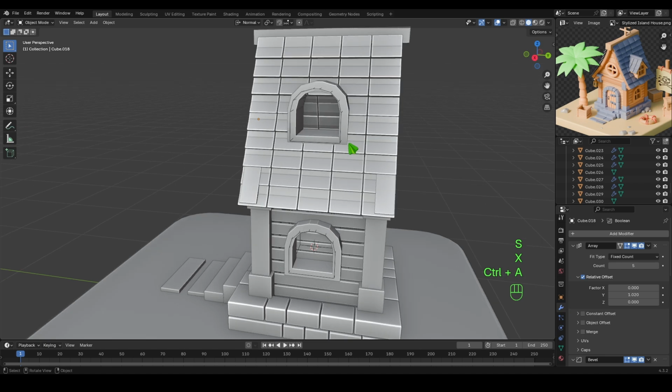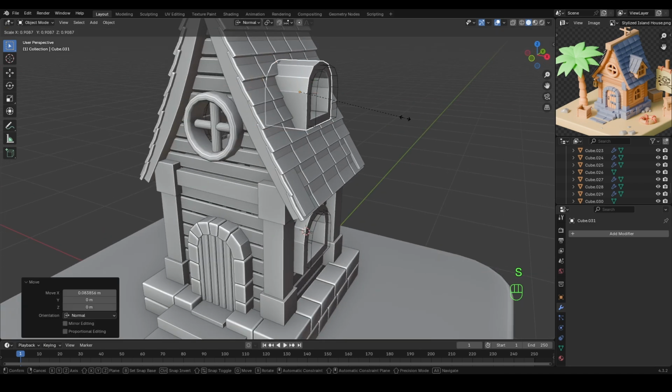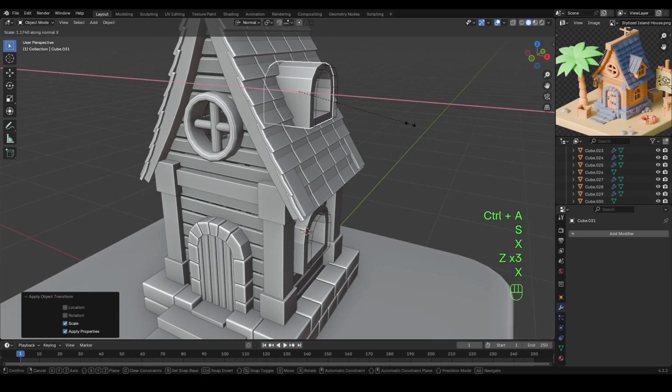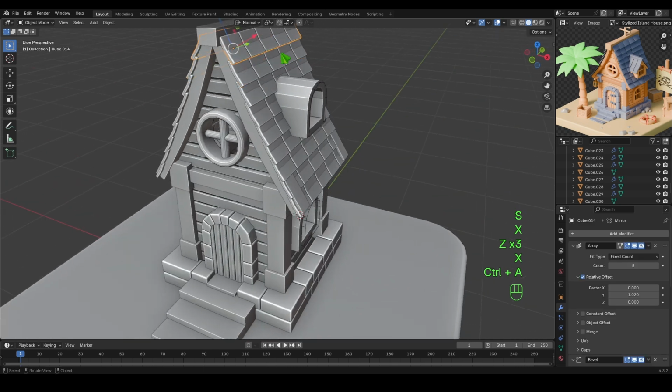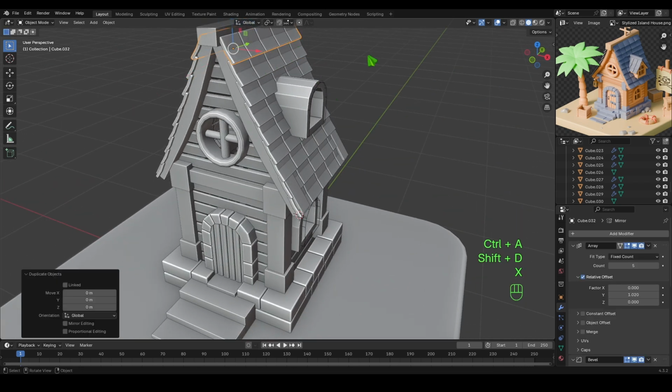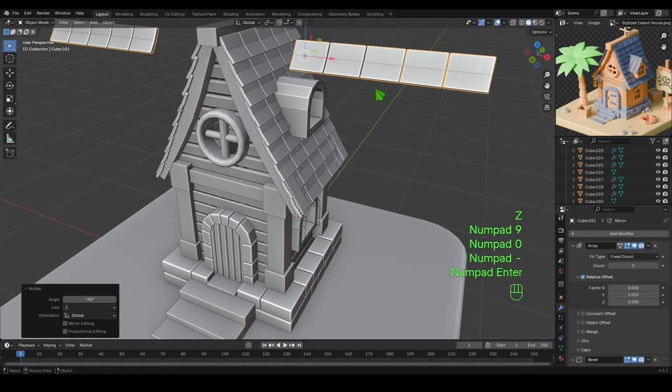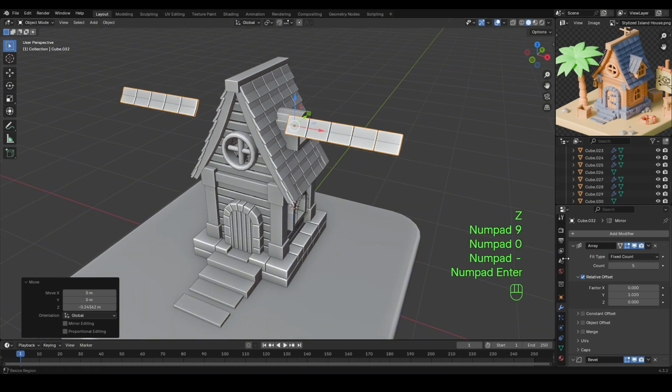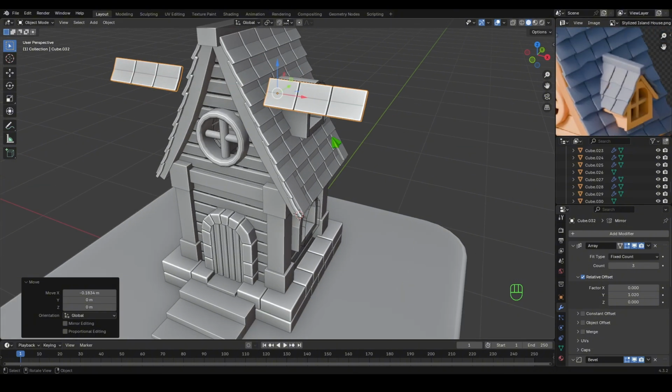Now we have got this sort of a thing. Okay, that looks nice. And let's move it here and make it smaller. Let's do scale. Alright, let's Shift E to duplicate. Okay, let's change it to global now. We need it here. Rotate to minus 90 degrees. And let's go to array modifier and put it to 3. Yes, there was 3 here. Okay, let's go.